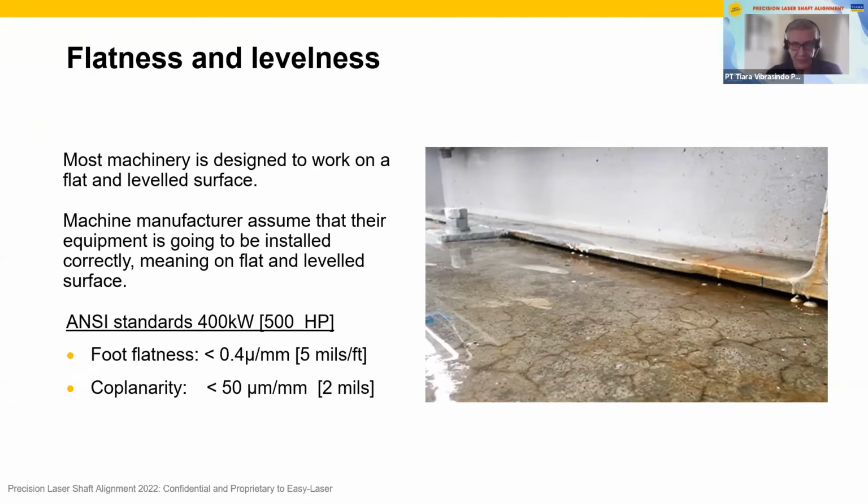On the other hand, besides the American standard, we have the International Organization for Standardization, the ISO. There are existing standards for centrifugal pumps for petroleum, petrochemical and natural gas industries. That is specifically ISO 13709. You can find this information, of course, on the internet. And it says clearly that the corresponding surface shall be in the same plane within 150 micrometer per meter. Now try to imagine how much is 150 micrometer in flatness and level per meter of distance or in area on a base.